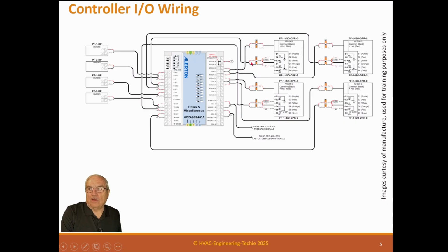and it shows what color wire. The red wire is here, the black wire is here, and these are crimps actually. And these are the wires coming from this actuator. This is a damper, and it shows what wires to leave open, not to wire. So this is a completely great diagram. This contractor's learned not to leave it to chance. Don't leave it to a field guy to make up his mind how he's going to wire these, because he'll do it wrong, and that's a problem. By having the drawing, if he makes a mistake, it's because he didn't follow the drawing. So anyway, these are the inputs and the outputs for this device.